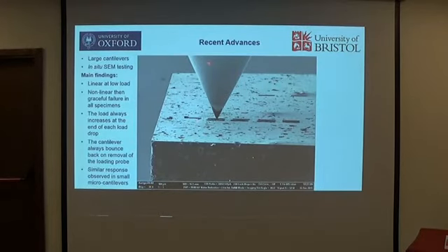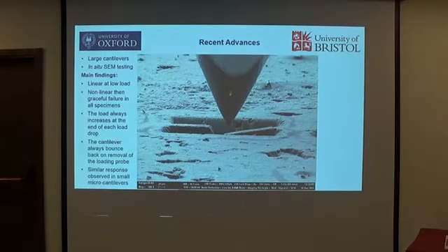Lastly, this is just a recent quick experiment. People always argue with me that the cantilevers are made too small because there are lots of pores in the middle, and that's why the data is very scattered. So what I did, another thing, is in situ testing in an SEM chamber using a nanoindenter. These tests are on very large samples. By large, I mean about 200 micrometers in length. So that's one scale up.